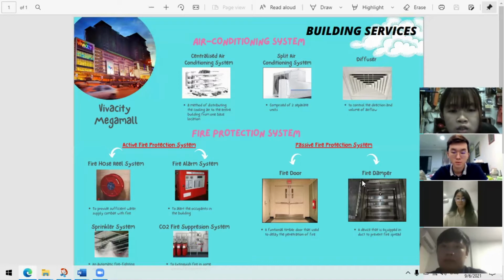The outdoor unit usually consists of compressor, condenser, and fan, whereas the indoor unit includes evaporator, filter, and fan. There are 7 steps to install the unit. First, select the location for the indoor unit. Second, secure the mounting bracket to the location selected. Third, drill the hole for piping. Fourth, place the pipe and cable through the hole and connect them to the indoor unit.